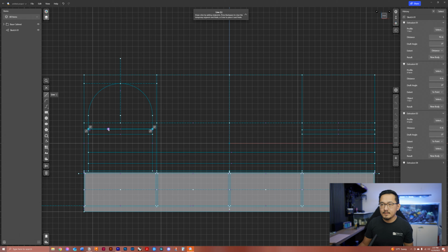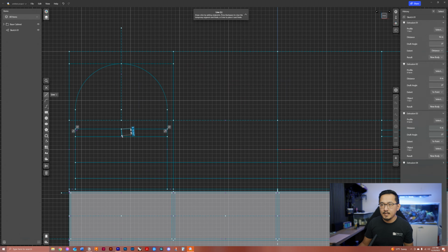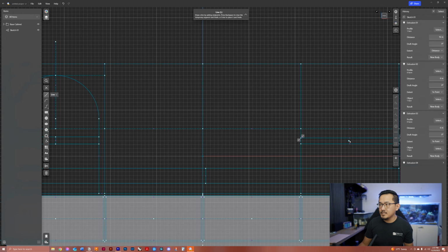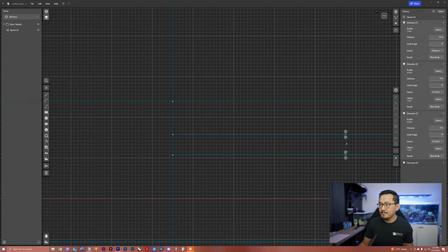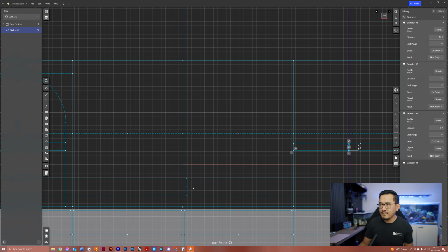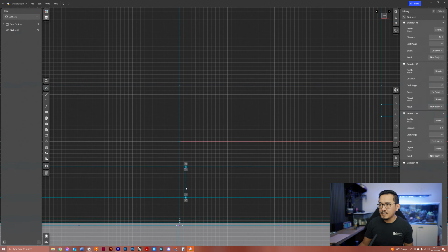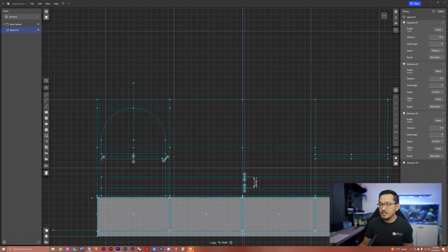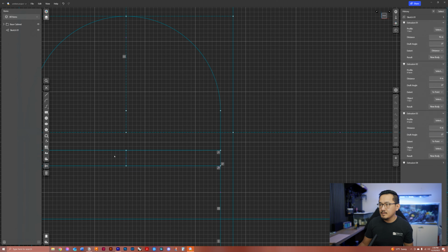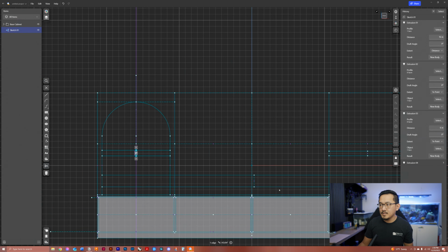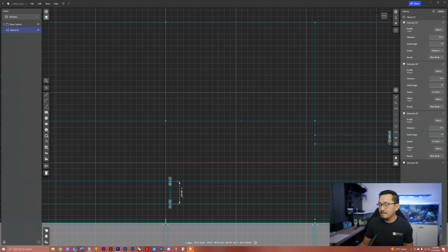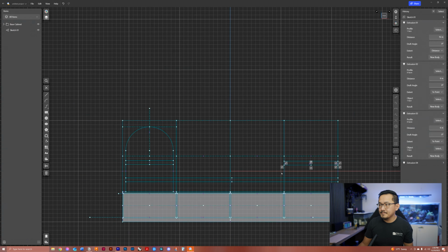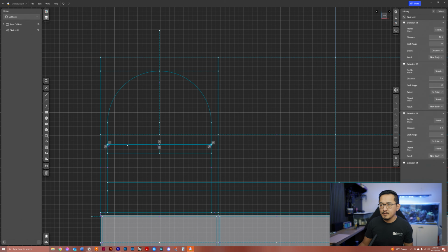All right, so now we've got the shelves drawn. I'm going to draw a midline here that connects each of the shelf lines, the upper and lower shelf lines. And we're going to hit equal on these, like we've done before. Make construction. I'm just going to re-highlight these and hit the equal button. So now all of our shelves are equal distance or equal thickness.